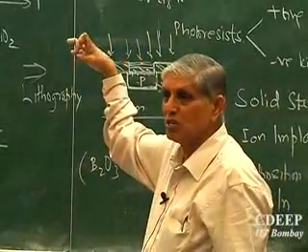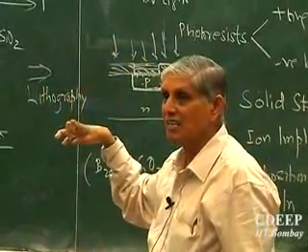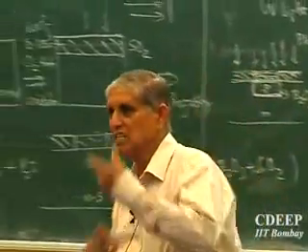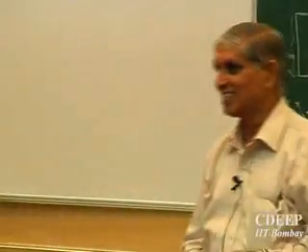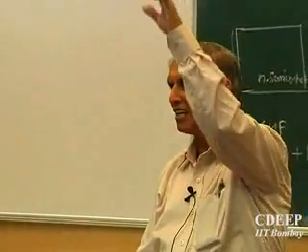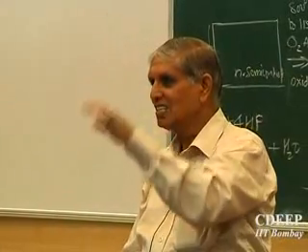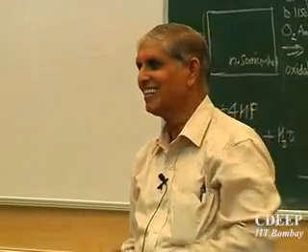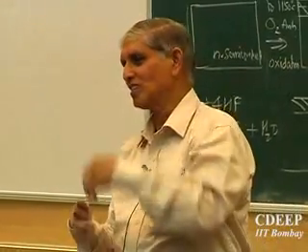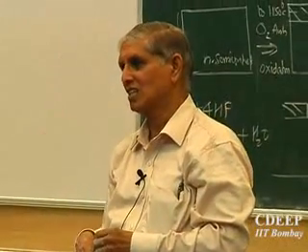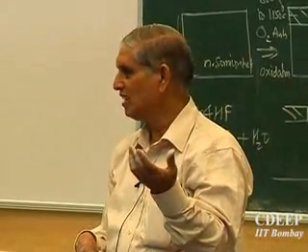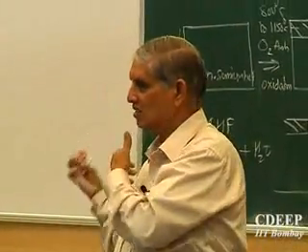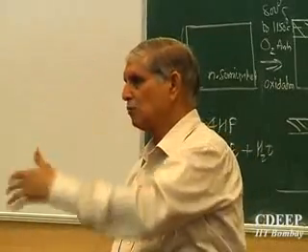Since they have huge energy, they hit the silicon lattice, and what do they do? They will start losing energy because they are hitting, but silicon will also get displaced. So now ions can start entering the silicon lattice. Is that clear? They will displace, get in, displace, get in, and as long as you do this, to that much depth these ions can get in. Then you drive in again, so you can create more depth, then you remove the ions and just heat again as normal, and you will get the junction deeper wherever you wish.